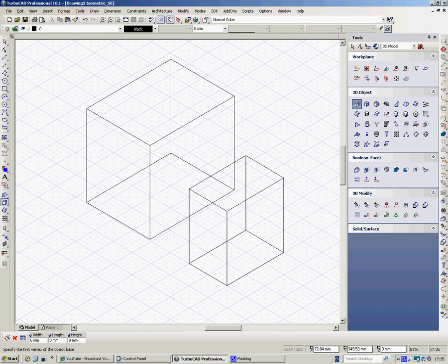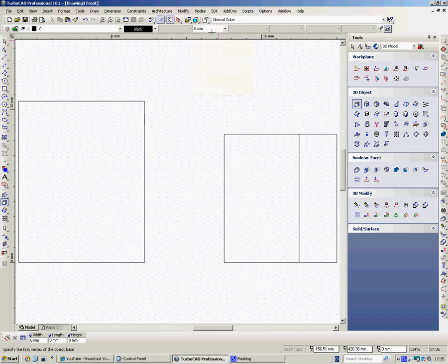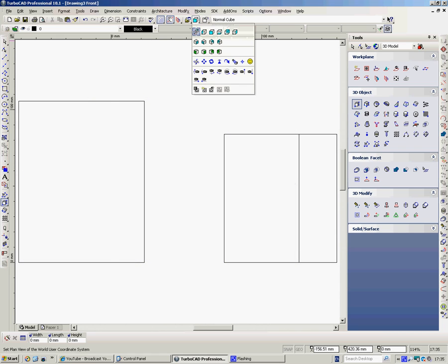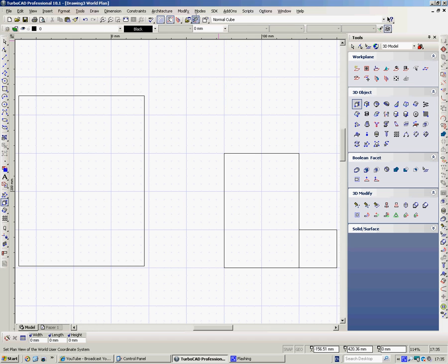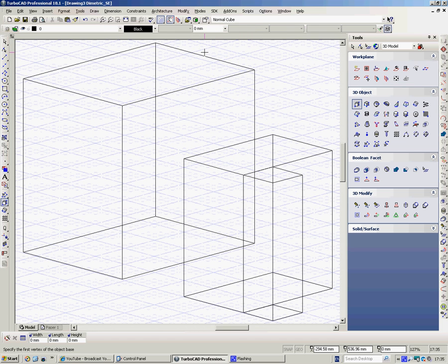I've also got my other usual tools. I can snap to a V for a vertex there, G for a grid there, take it up. If I want it to be the same height, I can snap it to that vertex point there, or I could use N for nearest graphic, and there it is. And from the standard views I can look at it as a side elevation, as a plan. I can look at it various other ways in 3D if I wish.